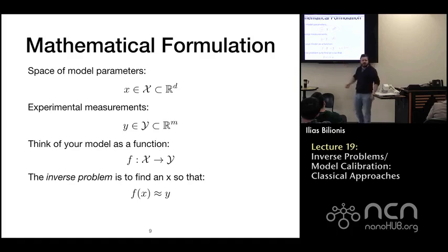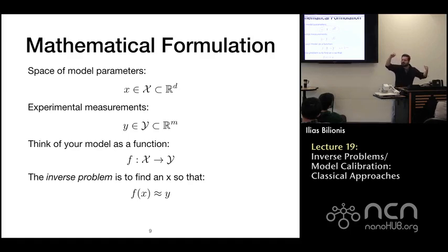Now this evaluation, of course, may be a little bit complicated. So somebody gives you, let's say, the permeability of the ground in a text file. You convert it in the right format. You generate a mesh on which you solve the two-phase immiscible flow equations using, let's say, finite volumes. And then you post-process the result to extract the pressure and the oil concentration and water concentration as a function of time at two well locations.